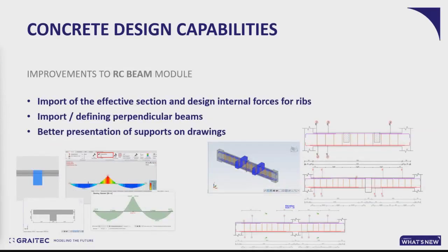Now, 3 quick points related to improvements to the RCB module. First, with the new version, when a beam is exported from Advanced Design to the RCB module, instead of a rectangular beam section, the equivalent T section is imported, with integrated design forces also.